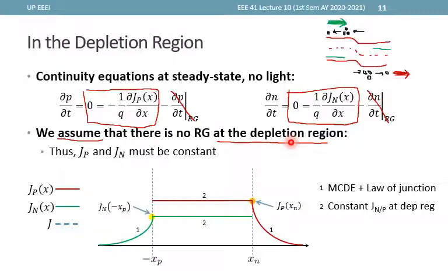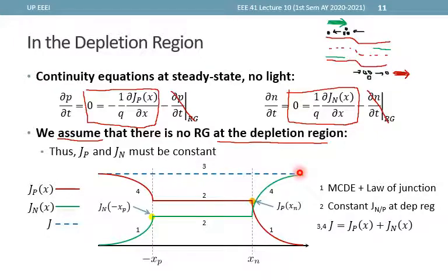Now after that, we also said that the total current must be constant, and since at this portion we know the value of Jn and Jp, then we can simply add them. So we add these two here, and we already get the total current density at this portion. But we said that the total current density must be constant, and therefore we can extend that line throughout the device. So given that we know the total value, say at this point we know Jp, the red one, then we can simply subtract to get the green one. And with that, we'll be able to determine the current densities for both holes and electrons and the total current density throughout the diode given some bias. Now this one is drawn not equal. This actually depends on the doping concentrations.